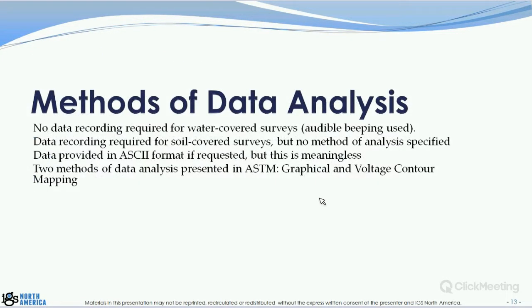So now we'll talk about data analysis. So we've established the distance between our survey scans, but the ASTM doesn't require data recording for water covered surveys. It's just simply listening to the audible beeping. So you're just walking back and forth, you're listening for the increase in tone, and when you hear that, you stop, you locate the leak, and then you move on and continue the survey.